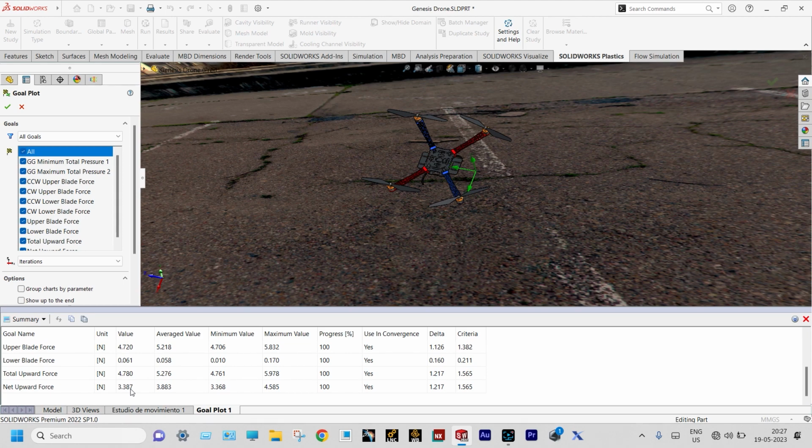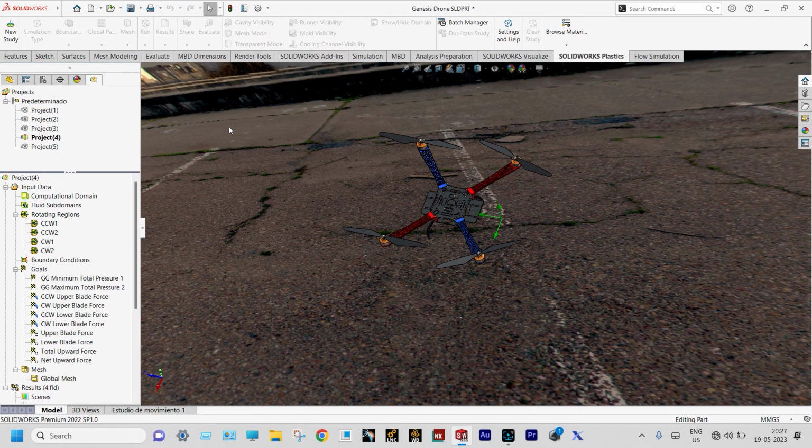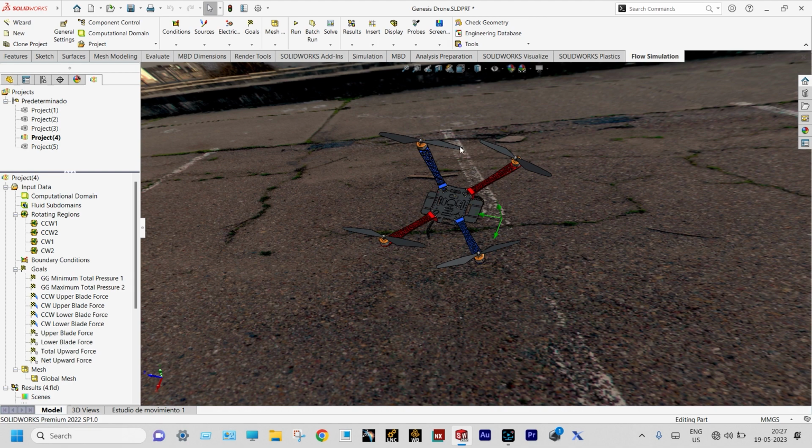Now, instead of doing these different analyses one by one, we could have done this as a single parametric study and could have generated more data, right? Now we'll see how to generate more data with a different set of angular velocities, right? So for that, we have to perform another analysis known as parametric analysis, right? We'll not complete this one. I'll show how to do this. For starting this parametric study, we'll start from here, solve, and it will be a new parametric study.